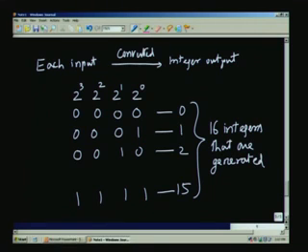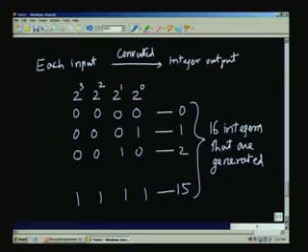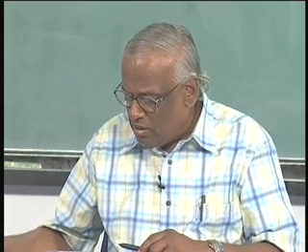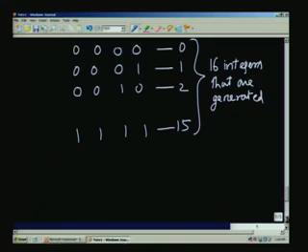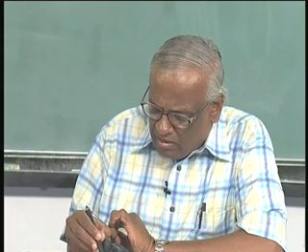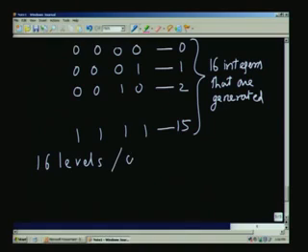That means, if the input of 1 volt corresponds to the last number, 1111 all high, and 0 corresponds to 0000, then 1, 2, 3 etc. correspond to the fractions. It is like dividing the range by the number of integers I can represent. In the case of a 4-bit conversion, I only have 16 levels. They are also called counts.